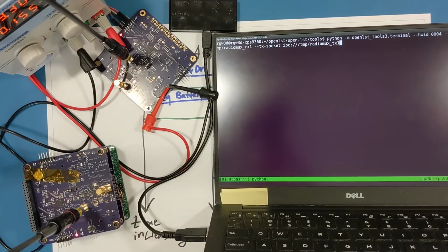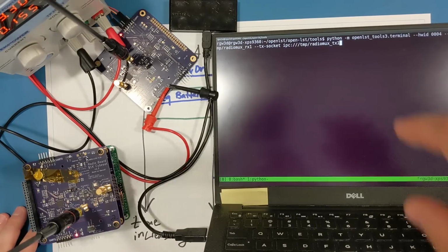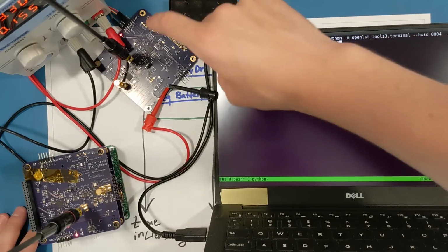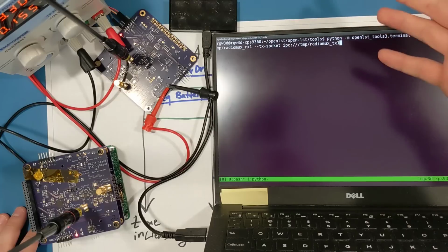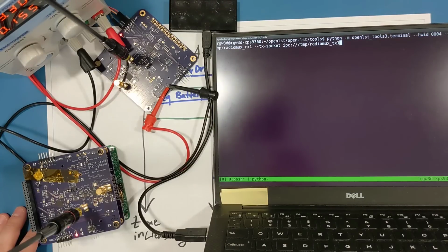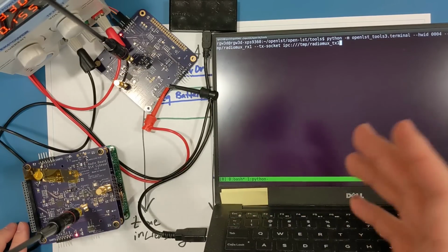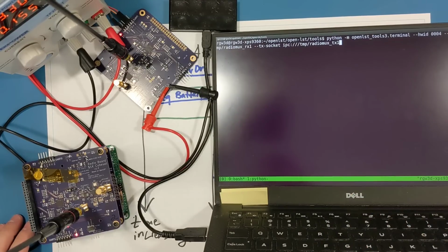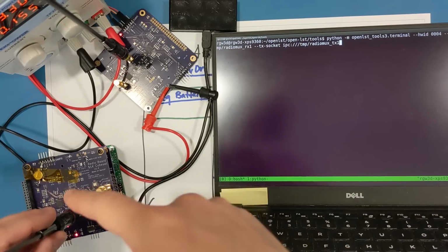All right, so I brought my computer into frame here. There's a terminal application that runs all of the OpenLST communication. There's a UART binary protocol that talks to this radio. All those details are on the OpenLST repository that I have forked. I've converted most of the scripts to run Python 3 instead of Python 2, which made things a little bit easier since I had to add in some Google Protobuf support in order to decode packets that I send from the CubeSat.